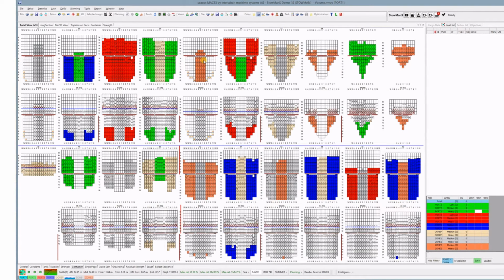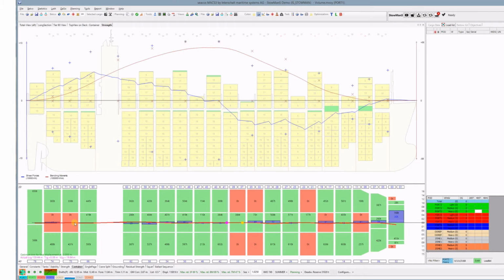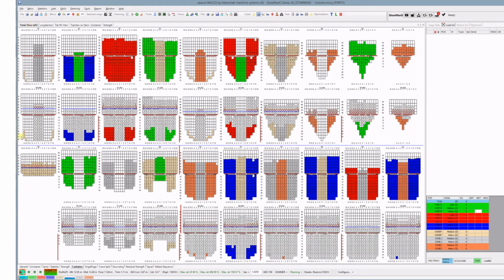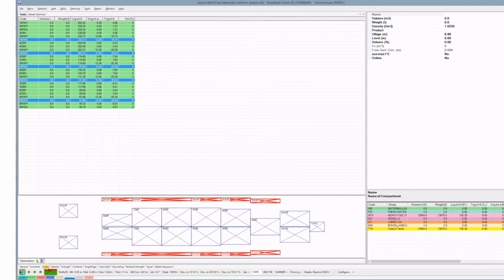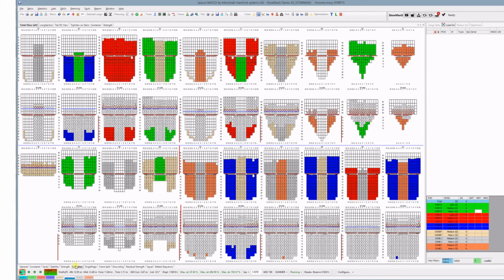Other approaches in the stow is to use so-called paired block stowage, where we say we stow the same POD in wings and center, and we also try to minimize the torsion in each bay, so there's very little torsion in this vessel. Regarding the tanks, we were able actually to reach a trim quite much in the region of 1.1 meter without using any ballast water, so we used the containers to achieve that trim. But I might not be completely happy with this. What was made here might be okay, so let's just keep that.